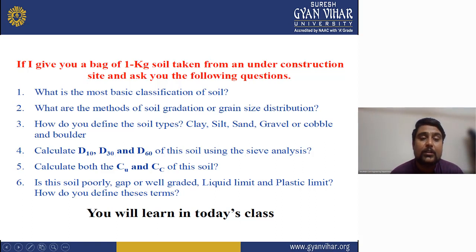What is the purpose of doing sieve analysis? This test is performed to determine the percentage of different grain sizes contained within a soil. The mechanical or sieve analysis is performed to determine the distribution of the coarser, larger size particles, and the hydrometer method is used to determine the distribution of the finer particles.